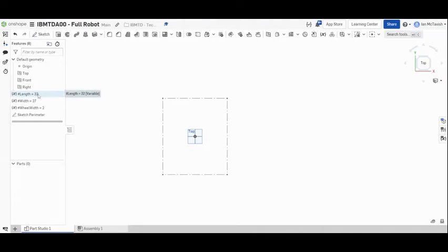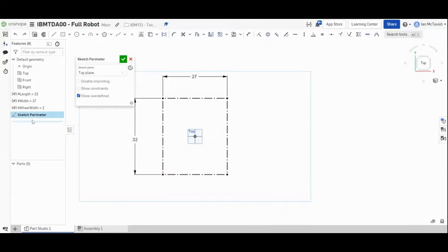So I've got my length, I've got my width. I'm going to go back into the perimeter, sketch perimeter, and this is up. Now I'm ready to create my sketch. So we're going to start with the rectangle, but this time we're going to select a corner rectangle. So the letter G is the shortcut for that. And again, that's the menu item, so it's right near the beginning. There's the line and then the rectangle. If you've got a small Chromebook window, you might see the first item in a little drop down, and then you can see everything else that's in the menu.